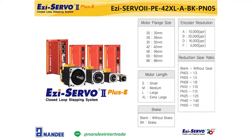A gearbox and a brake can be applied from a NEMA 17, 42 mm size motor, to a NEMA 34, 86 mm size motor. Gearboxes are planetary gearboxes, and gear ratio can be selected as shown in the table. The brake is a non-excitation type that activates when the power goes off. For example, you can use it to prevent the Z-axis load from falling. Please refer to the catalog for details.